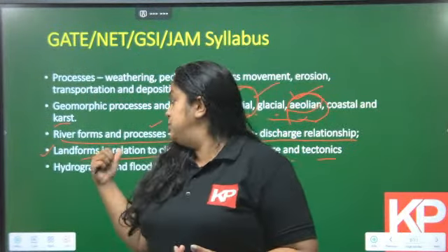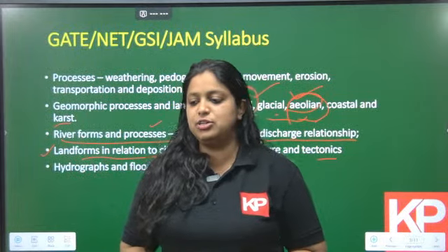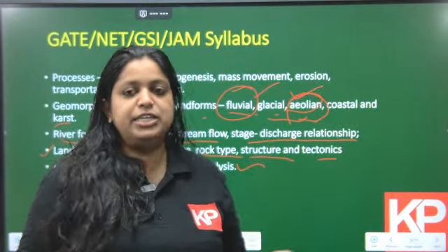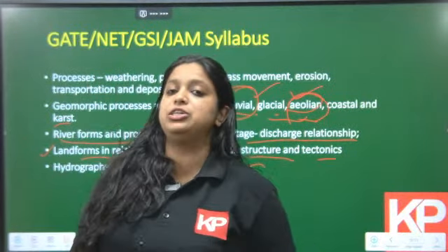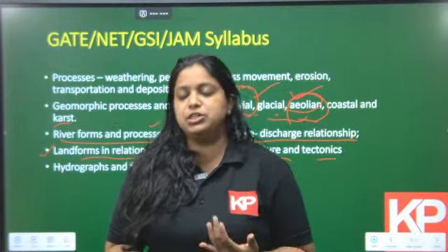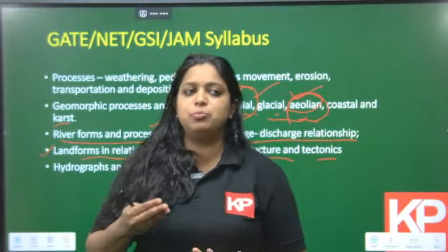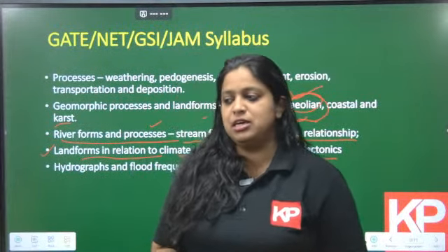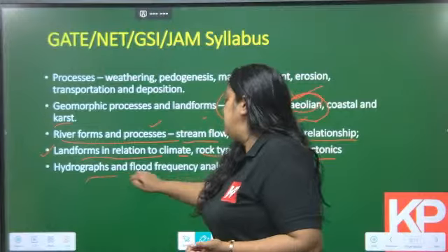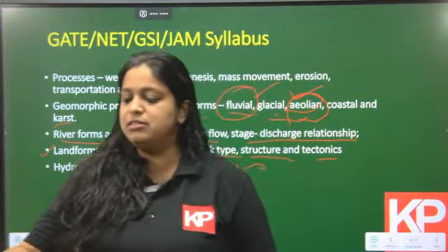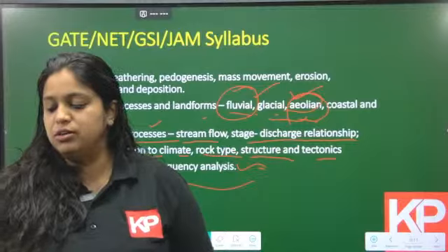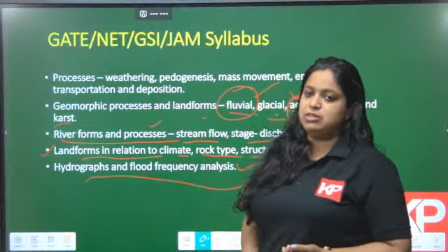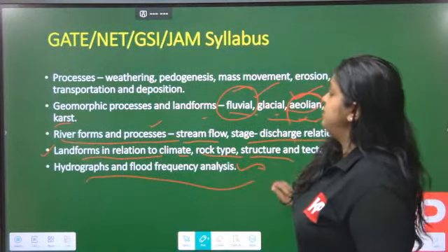Here, along with geomorphology, we will be discussing hydrographs, because they mainly ask questions related to drainage basin and how hydrograph variations happen based on the morphological changes of a drainage basin, or based on the vegetation present in the drainage basin, slope of the drainage basin, etc. Because of that, hydrograph or flood frequency analysis is done here along with the geomorphology section. So these are the different topics that we discuss in geomorphology.